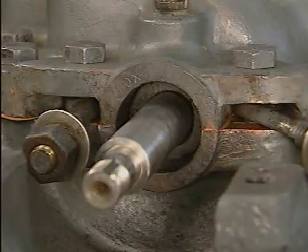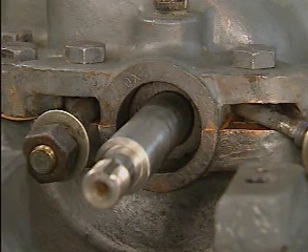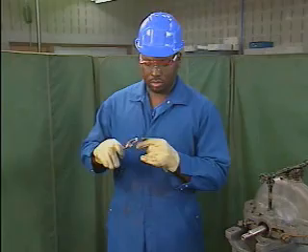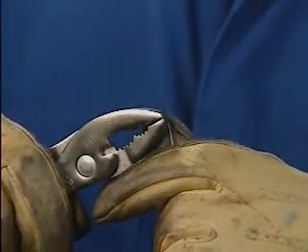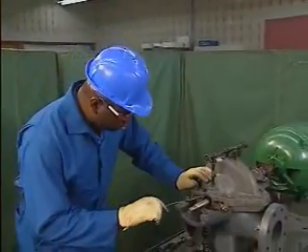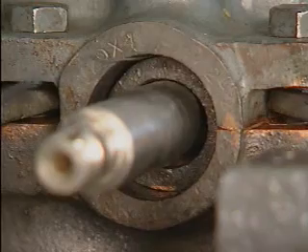On this pump, a lantern ring is positioned between two of the rings of packing. In order to remove the remaining rings of packing, the lantern ring must be removed first. To do this, the mechanic takes a short piece of stiff wire and bends one end to form a small hook. He inserts the wire into the stuffing box between the lantern ring and the wall of the stuffing box.